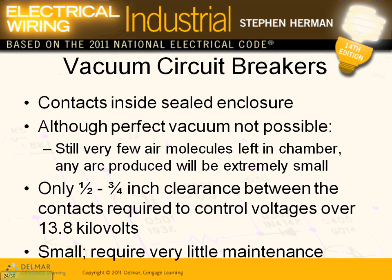Vacuum circuit breakers, we talked about vacuum. They take the tube, they get the air out of the tube, so you're not going to get any ionizing, and they're used mostly for high voltage, of course. Look at the clearances. This is my interest. The clearances between the contacts. Actually, you can get from half to 3/4 of an inch between the contacts. Who cares? It makes vacuum circuit breakers smaller in size than oil circuit breakers. So they have an advantage. Smaller sizes, a lot of advantage to it. You can put it in tight locations. Little maintenance.